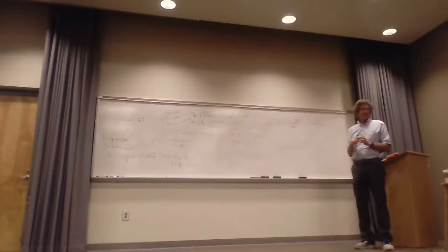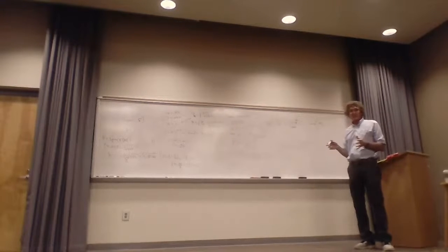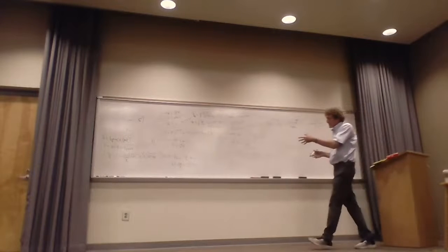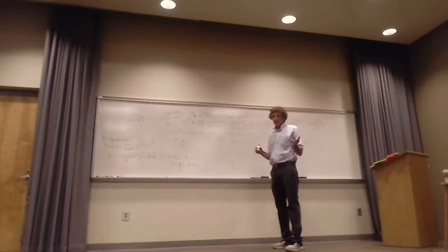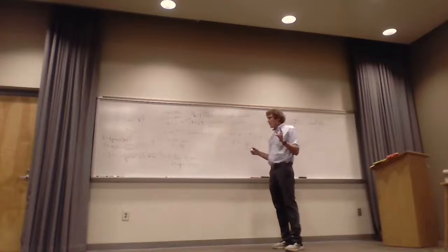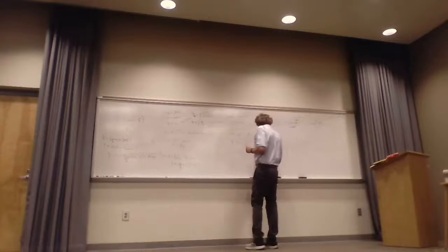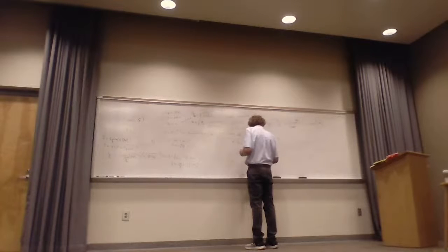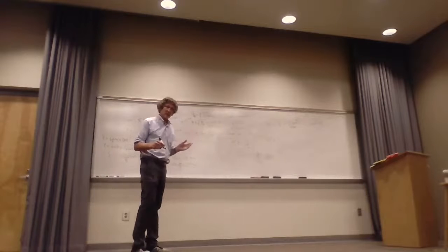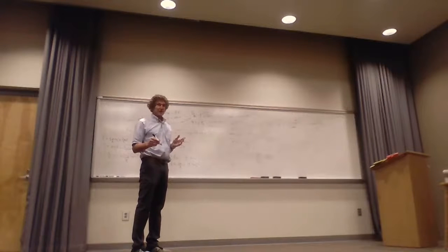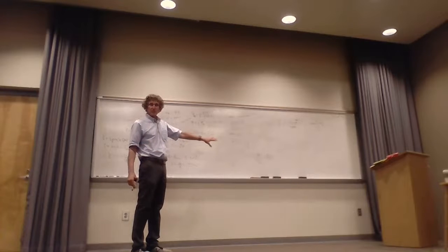Magnetic field. All right, and this is one that gets people, by the way. So I gave you the E field. How do I get the magnitude of the magnetic field? Now it's a propagating wave for starters, right? If it wasn't propagating, we can't do this. But we know the magnitude ratio of E at a given point in space-time over H is equal to eta, the magnitude of the intrinsic impedance. I just care about magnitude. If you want the exact value, we can get it, and maybe I'll show that next. But if I just want the magnitude, do y'all agree that that works?